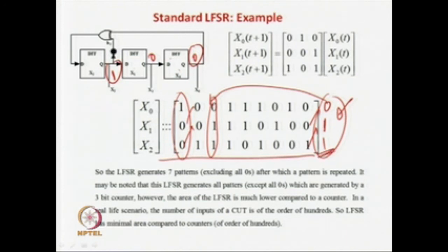So this expression is what you can call an exhaustive polynomial. It generates all the patterns possible. So accordingly you can decide on the seed, and then you find that all your important patterns were up to here, and after that you can reset. So basically what we have achieved, or you can also think that my important patterns are here, so you can then start with this one as a seed and go about this way.